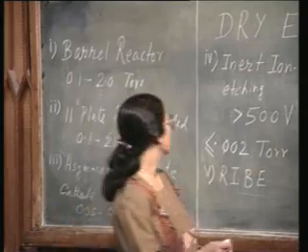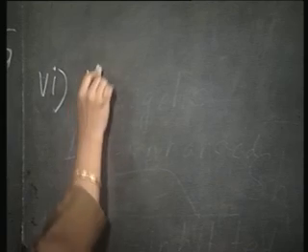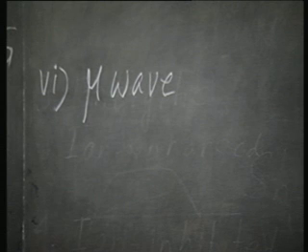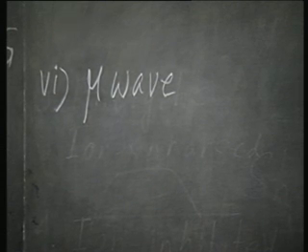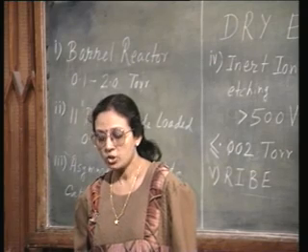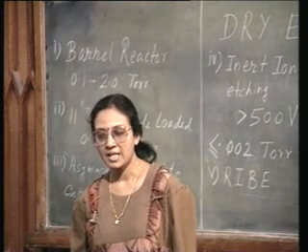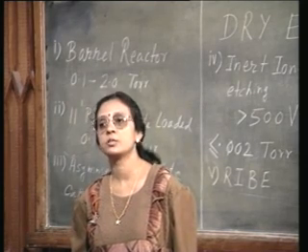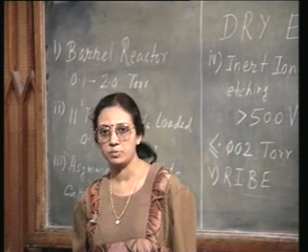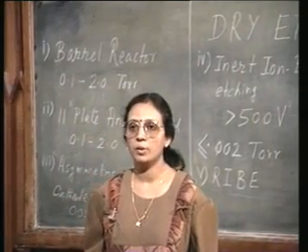In contrast, we have microwave plasma. Usual frequency is 2.45 gigahertz. So, you can have very dense plasma at microwave frequency, and this will have very low sheath potential. You may ask me why I need this very low sheath potential. This is when you are particularly bothered about damages.